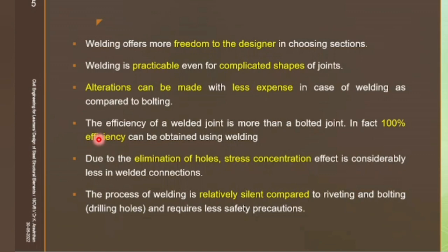But in case of weld, you don't have any holes at all. So whatever welding you provide, 100% of the force is transferred to the member and the connecting plate. Due to elimination of holes, stress concentration is eliminated, and the process of welding is relatively silent when compared to riveting or bolting.